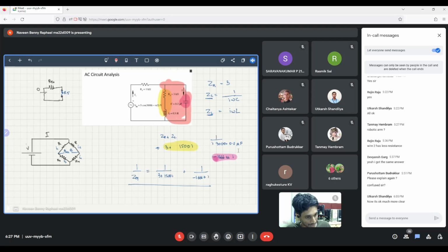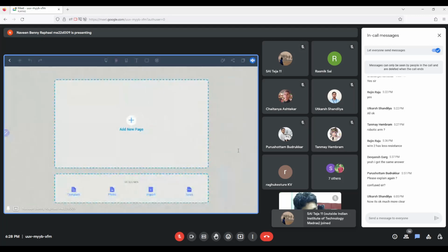It's essentially the same equations. The only difference is we are now considering current, resistors, and everything in the complex plane, because that makes the maths much nicer. Even though it's very frightening in the beginning, it makes the math much nicer when you solve it properly. The other way, you can theoretically solve the entire thing using KVL and KCL. However, those will give you differential equations, and we really don't want to be touching differential equations now. I mean, solving differential equations is fine, but it's always nice if we don't have to, right? Because if you're solving this using complex numbers, it's just essentially the same algebraic solution. So yes, that concludes the AC analysis.